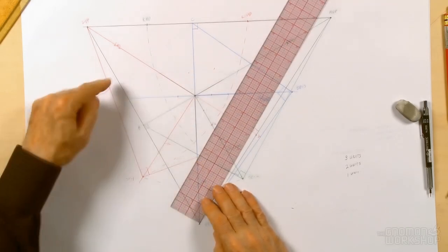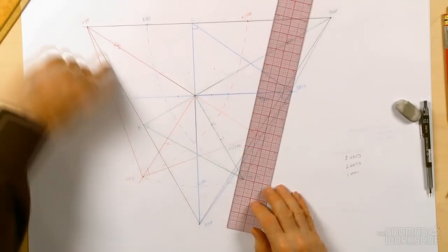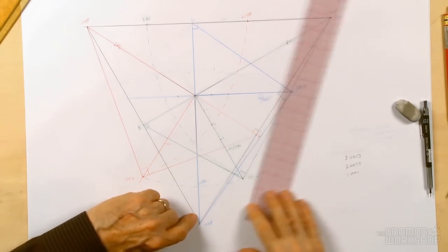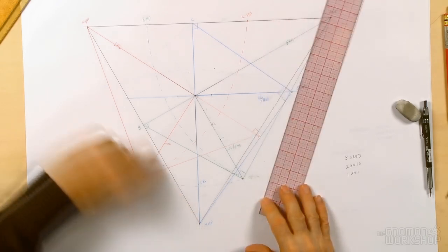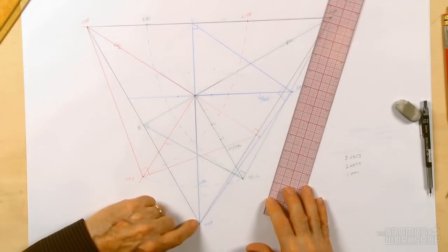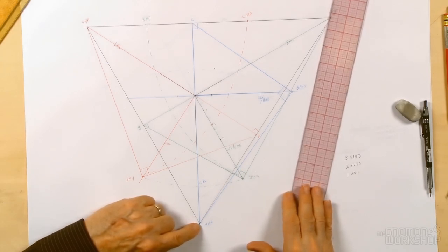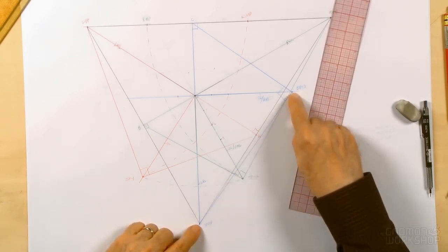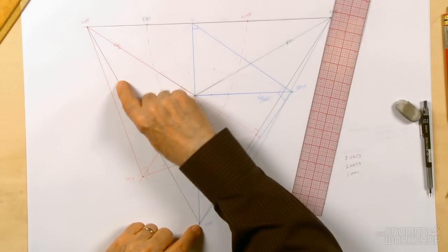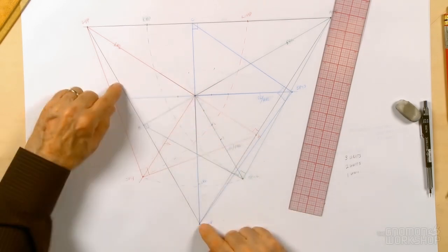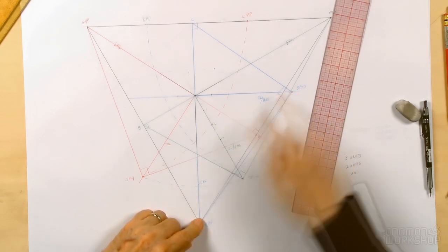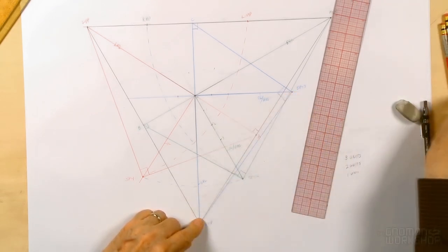Once again, a measuring point. See, this is now called a horizon also. Remember, those 3 lines interconnecting the vanishing points are called horizons. Okay, on this horizon, I'm going to find a vertical measuring point by measuring the distance from the vertical vanishing point to station point 3 and measuring that same distance on this horizon. And remember that definition again. A measuring point is a point on the horizon, the same distance from the vanishing point that the station point is from the vanishing point.